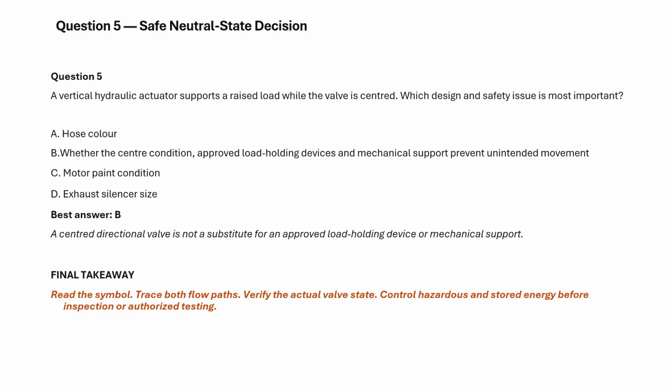Question 5. A vertical hydraulic actuator supports the raised load while the valve is centered. Which design and safety issue is the most important? A. Hose color. B. Whether the center conditions, approved load holding device and mechanical support prevent unintended movement.